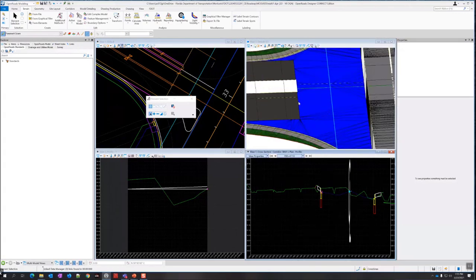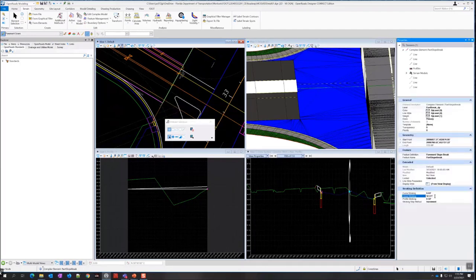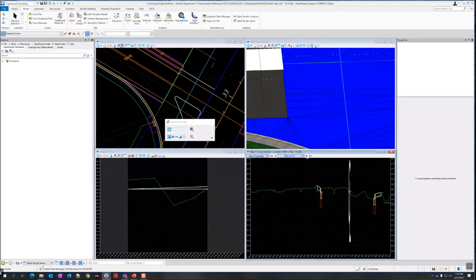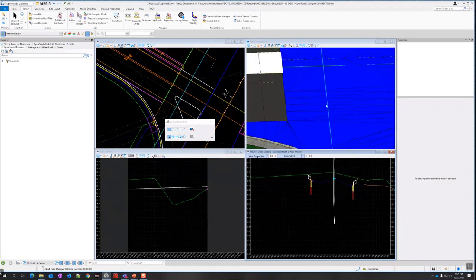If you wanted to have it tighter over here on this line, you could also change the stroking definition there. So that's something that is worth playing with. So I'm just going to change that to 5 as well. Notice that it made a lot of triangles across here that we didn't have before. It was just one large triangle. Now it's a bunch of smaller ones.